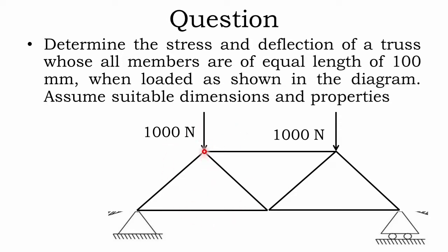So now let us see how to find out the height of this point. I know this is 0, 0, and this point is going to be 100, 0. The beam length is 100 mm, and this point is going to be 200, 0. This is easy to plot in Abaqus sketcher. But how to find out this point? What is the xy coordinate of this point? I have to find that out first.